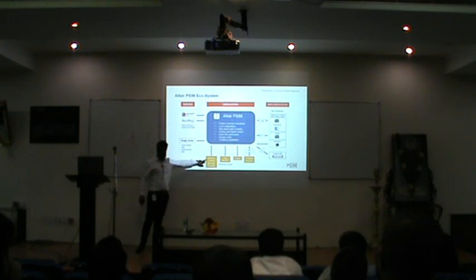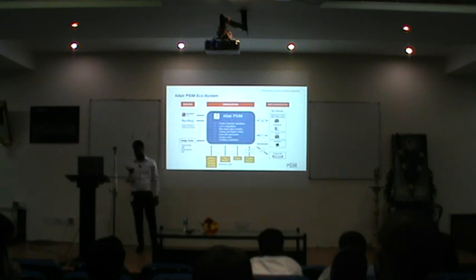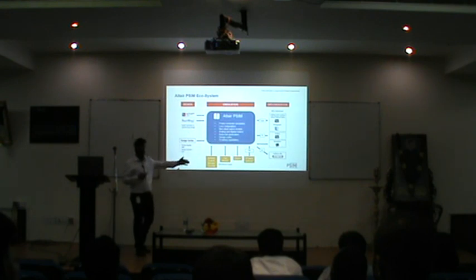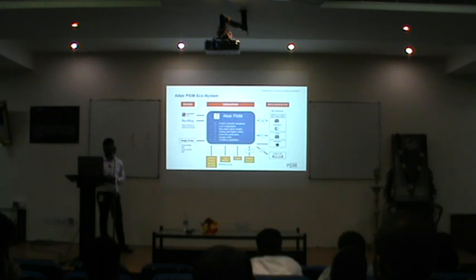ActivateEmbed is our own tool for co-simulation. Flux and FluxMotor for motor design can be integrated, after the acquisition we can do that. So these are new features, which we integrated after the acquisition. And then you have LTspice integration for SPICE simulations, and integrating with FMI for third-party integrations. This is the overall ecosystem of PSIM.